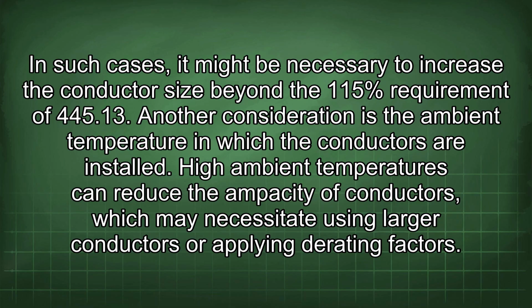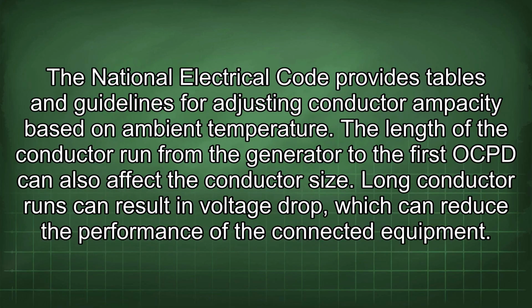In such cases, it might be necessary to increase the conductor size beyond the 115% requirement of 445.13. Another consideration is the ambient temperature in which the conductors are installed. High ambient temperatures can reduce the ampacity of conductors, which may necessitate using larger conductors or applying derating factors. The National Electrical Code provides tables and guidelines for adjusting conductor ampacity based on ambient temperature.